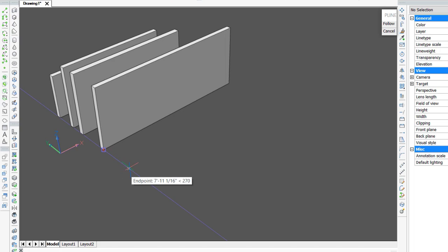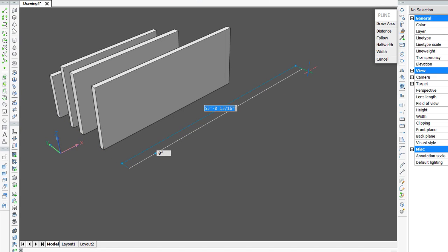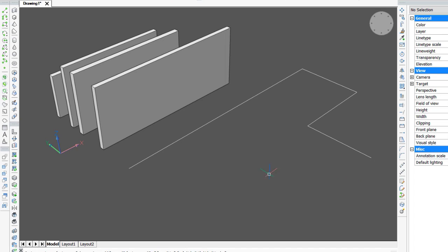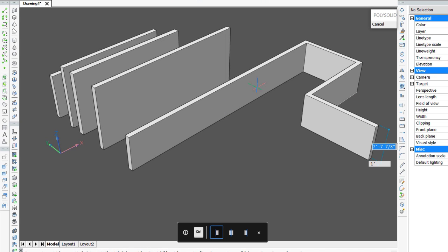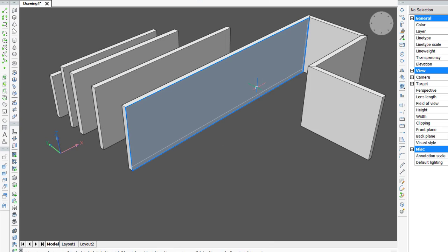Imagine a perimeter footprint has been drawn that is a single polyline. Initiating polysolid, we'll set justification to left, which makes the polyline the outer edge. Next, we'll select Entity and select the polyline. At the click of a button, we have 4 independent walls created from that polyline.